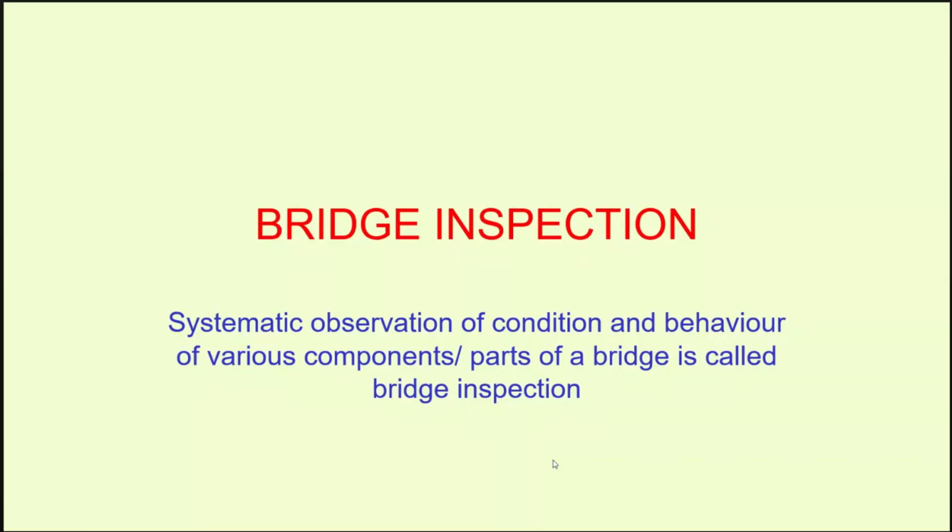Now if the same structure is being made with steel, you can say steel arch bridge, a steel pipe, or a steel orthotropic deck type of structure. So all things will be having a very different behavior. So we need to understand from the material behavior point of view. Behavior of concrete slab, and similarly behavior of steel slab, that needs to be seen, because the failure mode of concrete and steel is very different. Concrete generally fails under the tensile forces.